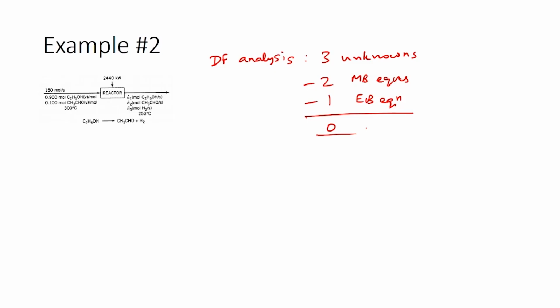So, for this we need to write the energy balance equation. How do we go about preparing it? First thing is to identify what system it is. This is an open system, you have material coming in and leaving. So, you would start with the open system energy balance equation, which is Q dot minus Ws dot equals delta H dot plus delta Ek dot plus delta Ep dot.